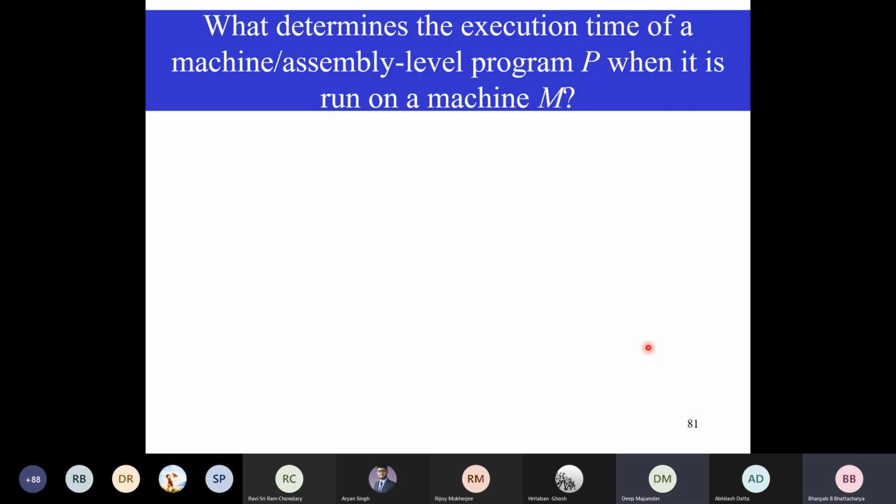The type of the instruction, like ALU instructions, probably take less time than load instructions, which access memory. Yeah, that is one issue, but we'll discuss later on this, because if the time of instruction varies, then there may be difficulty in synchronizing the pipeline, right? Because then it will be variable time instruction.